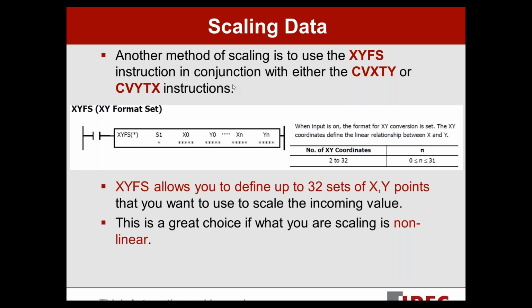Okay, now the XY format set, you guys can see the structure of the instruction here. We've got to have some sort of an input to turn on the XY format set. Okay, what this lets you do is you can define up to 32 sets of points, 32 sets of XY points that you can scale your value between.